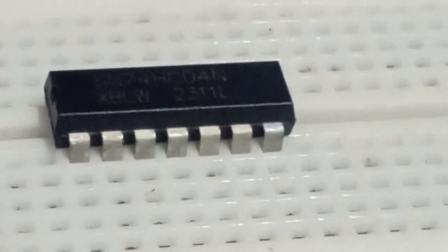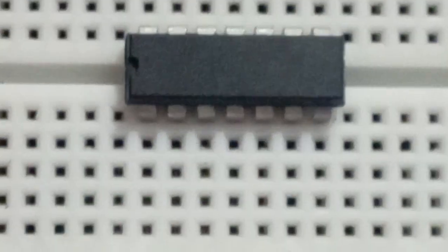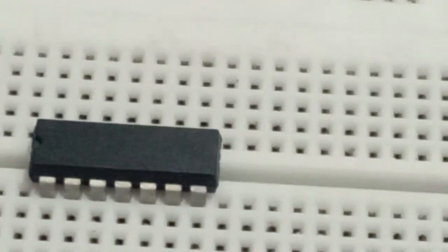So this is going to be the whole code. I have connected the IC in this way, with these pins on this side and the other pins on this side, and the IC must be connected in this way itself. This notch must be kept in mind, because wherever the notch is present, on this side starts the pin numbering, 1, 2, 3 till 7 here, and from here it is going to be 8 to 14. So this is the numbering, and this top one is VCC, that is, positive to the battery, and this side is going to be the negative side. Okay, this is how you are going to connect.